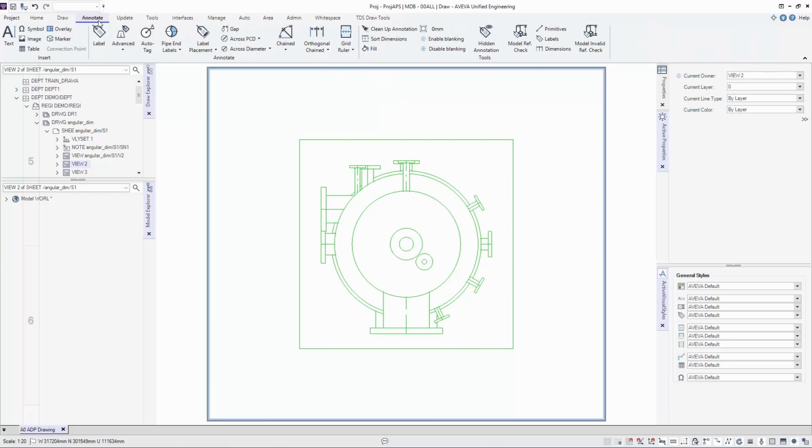We access the PCD pull-down menu, which lists several options for creating pitch circle dimensions. Each option provides a different arrangement, such as circular spacing, angular layout, or radius-based configuration. We select one of the options from the PCD menu. To define the pitch circle dimension, we pick 2 points, the center of the pitch circle and a point on the circumference of the arc.